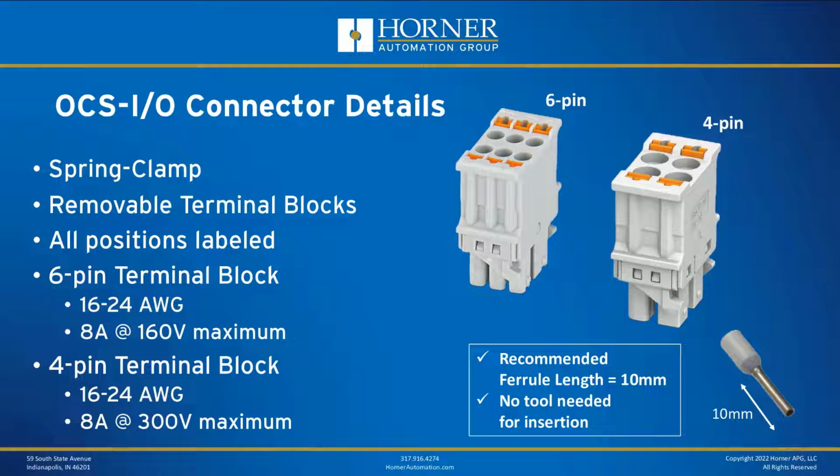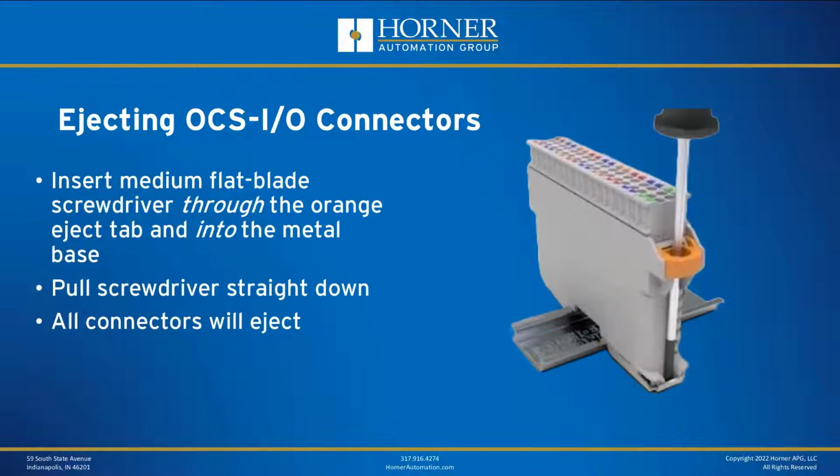Now, if you're going to use ferrules, the advantage to using ferrules, of course, is that there's several advantages. One, you don't have to deal with stray strands of wire. Another is, if you use ferrules, you can go ahead and insert the conductor into the terminal plug without a tool. Of course, to remove it, you're going to need a screwdriver, but to insert the wire, you don't need a screwdriver or any other tool if you do use ferrules. And the ones that we would recommend would be ones that have a length of 10 millimeters. Those seem to work the best.